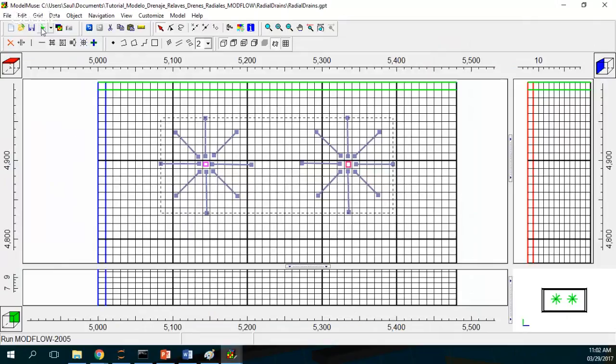Before that, if we play around with our drains like this, our drains have a thickness of 10 meters, and this is not true because actually our drains will be limited to maybe 1 meter or 30 centimeters depending on the drilling technique. So we need to do a refinement here. The topic about refinement is that you can get numerical instabilities if you do higher refinements, and you have to play around with the parameters in order to get convergence.